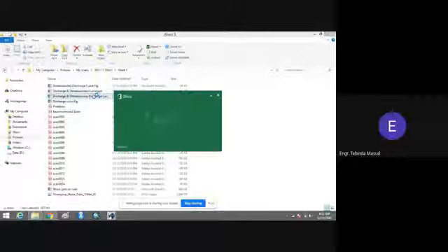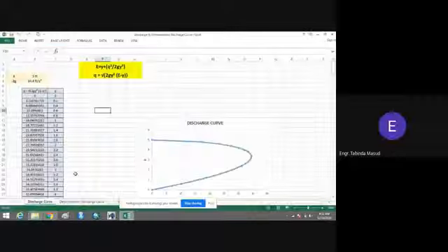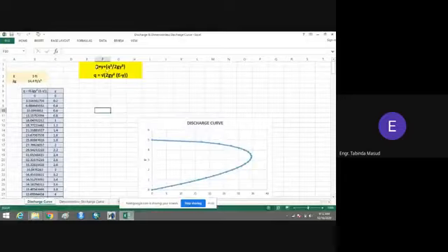Okay, let's see how we can develop the relationship. You can see here that this is the actual equation: E is equal to y plus q squared divided by 2g y squared. And this is the simplified form for q: q is equal to the square root of 2g y squared into (E minus y), which we have developed already.